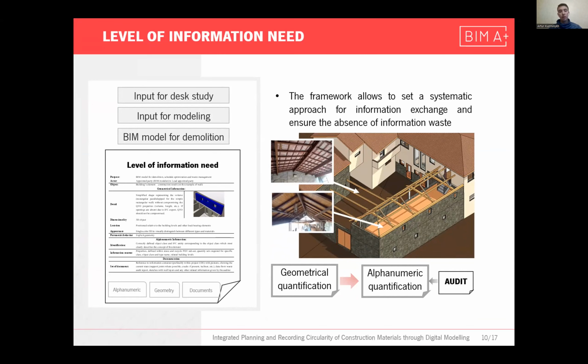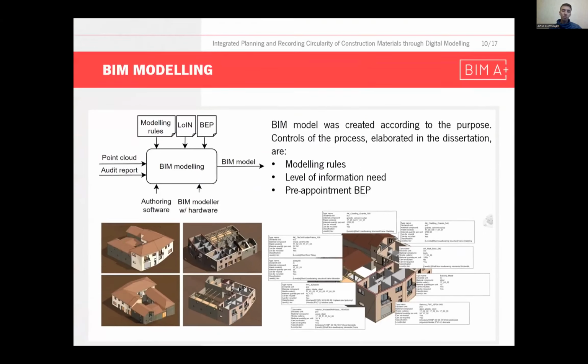The major principle formulated here is that the effort invested in the BIM model should not overcome the possible benefits of the work itself. For example, roof system. Defining its full geometry could require considerable time without the use of automation methods, and the benefit could be questioned. Therefore, for quantification, the elements could be described in alphanumeric datasets with values of materials weight distribution per length, area, or volume. However, it was stated that more case studies are needed to consider other possible peculiarities.